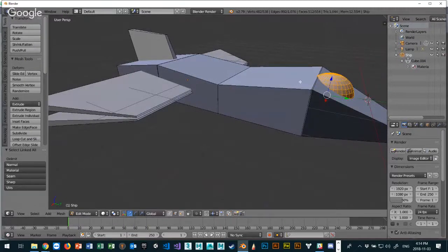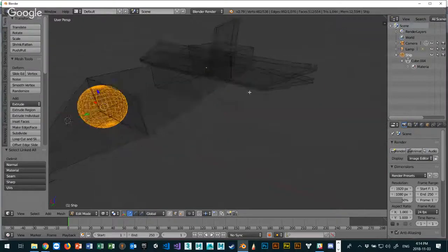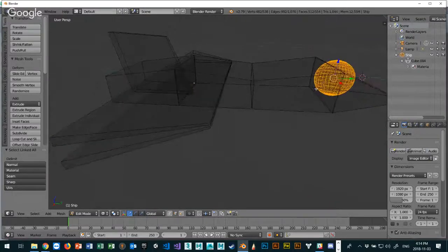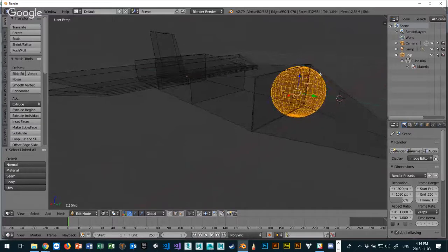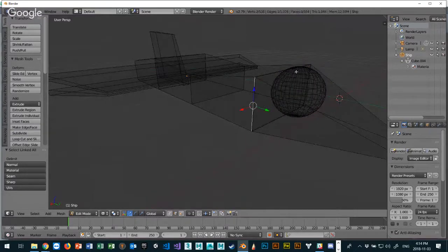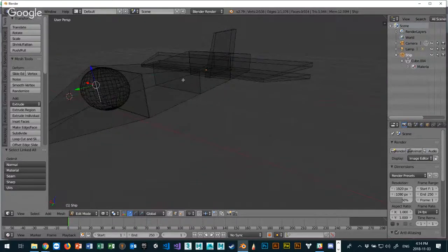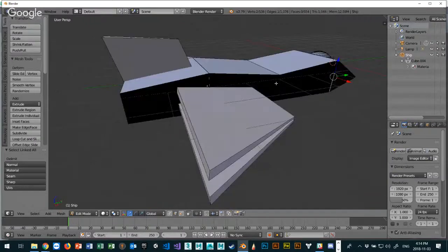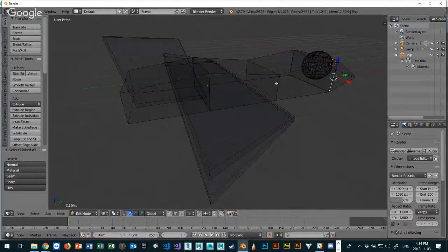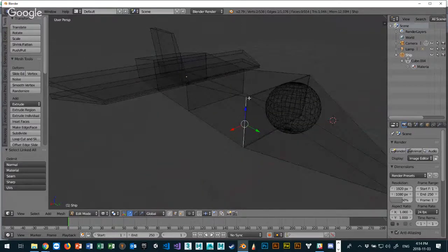I press the Z key. This is wireframe mode, where I can actually ghost all the other objects that I'm seeing, and I can see just the shapes of the objects in wireframes. You can see now, if I just click away here, that this sphere is inside of the other object, like this. Okay? So the Z key allows me to go from solid mode to wireframe mode. And this is great from a visualization perspective to understand what's happening.